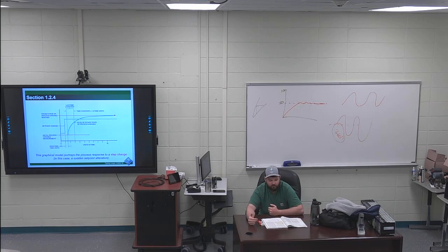Page 5, right after the caution on page 5, first 2 sentences are highlighted. An integrating process, in contrast, is not self-regulating. Once the controller output changes, the process will begin to react and will keep changing as long as the controller output is in the new position.